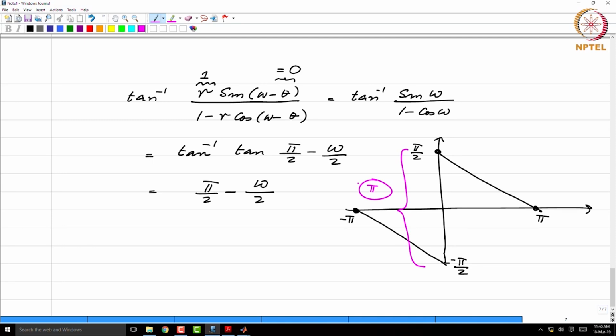In this particular case, the 0 is at omega equal to 0, because all that will happen is when theta changes, this curve will shift to the left or to the right, that is all. And in this case, this happens to be centered at omega equal to 0, because that is where the 0 location is. So, the jump will occur exactly at the location of the 0, and the slope of the curve happens to be minus half.